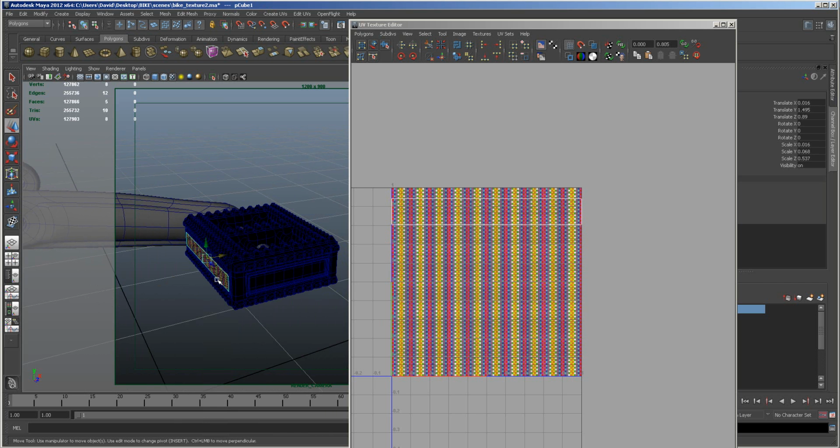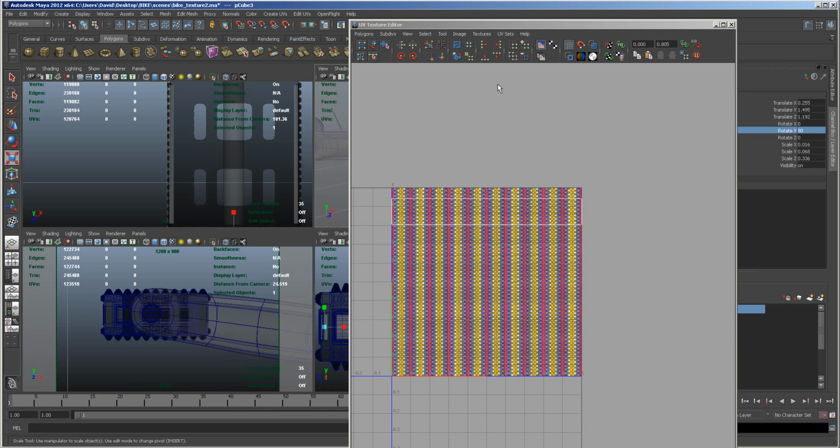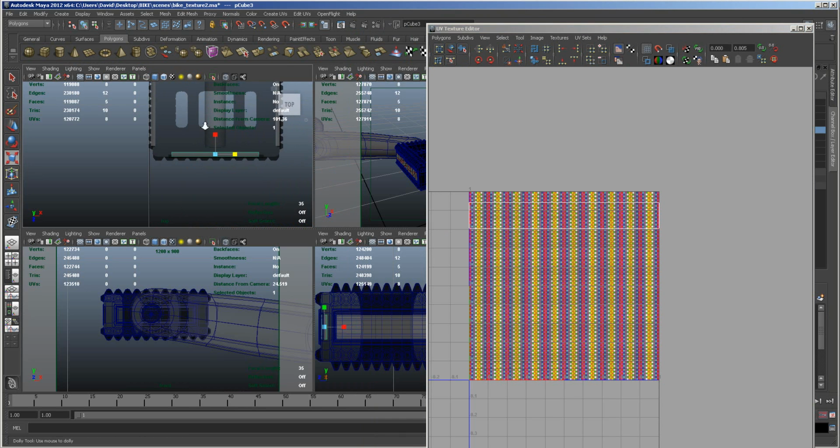I'm going to press Ctrl D, I'm going to press R on the key, E on the keyboard, and I'm going to translate it around the Y-axis 90 degrees, like so. I'm going to press the W key, bring the blue, bring it forwards, get it into position, bring it across. Now I need to scale it, so I'm pressing the R key and I'm just going to bring this in. You might need to just jump into another view, something like this.